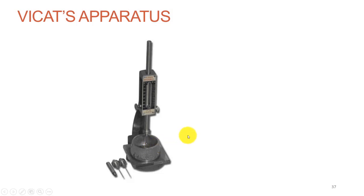If you have a penetration of around 5 millimeters observed from the bottom, then it would be called the initial set. For the final set, the penetration is about 1 to 2 millimeters from the top of this mold. So initial and final set we can check by this Vicat apparatus.